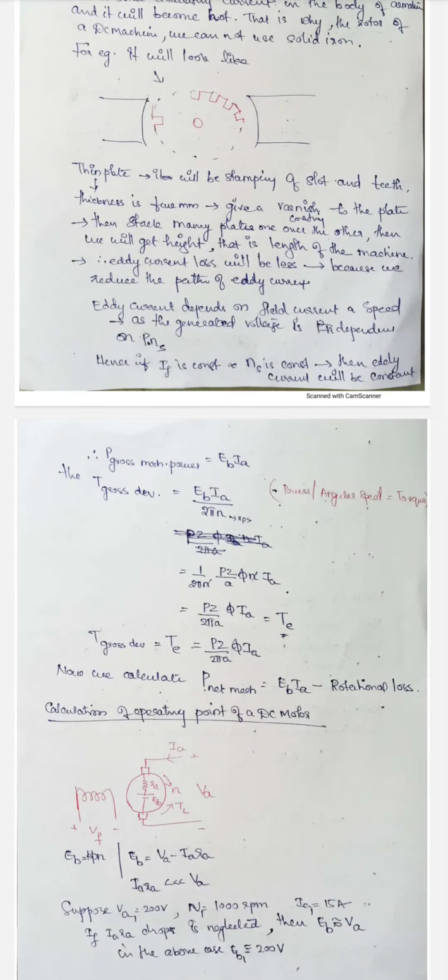Now, as far as this DC motor armature is concerned, whatever current is produced is AC current, which you know in the armature, because it is all induced. Induced is always AC, alternating. That is why there is a frequency, alternating current. That is why you are experiencing the eddy current loss. And so you should not forget that point also.